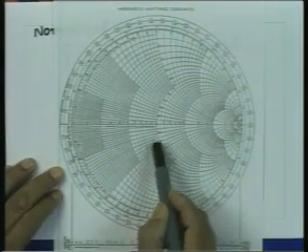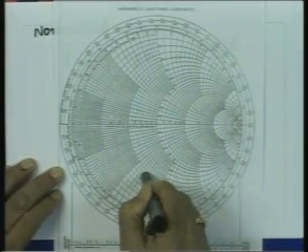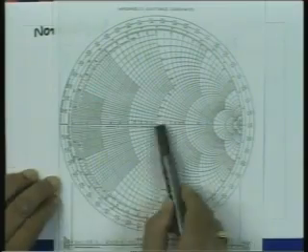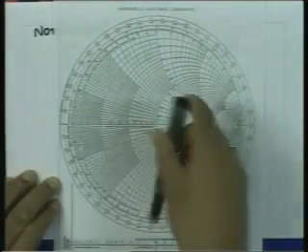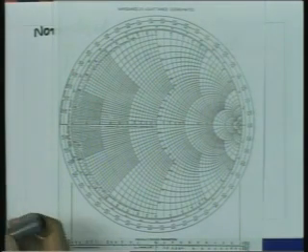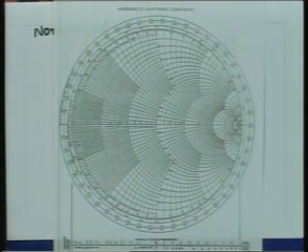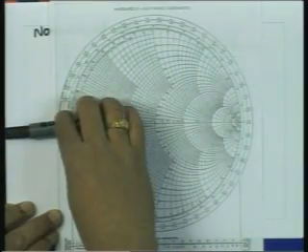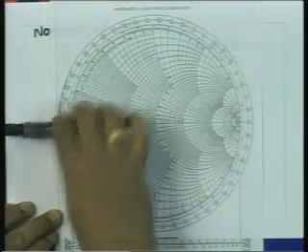However, if I do the calculation by using this chart for admittances, then the real axis will be on my left and the imaginary axis will be downwards. Normally, whenever we do the Smith chart calculations, we do not rotate the Smith chart. We follow this convention that the Smith chart is fixed, but for impedance the gamma axis is like that, whereas when I go to the admittances I get the gamma axis which will be like this.